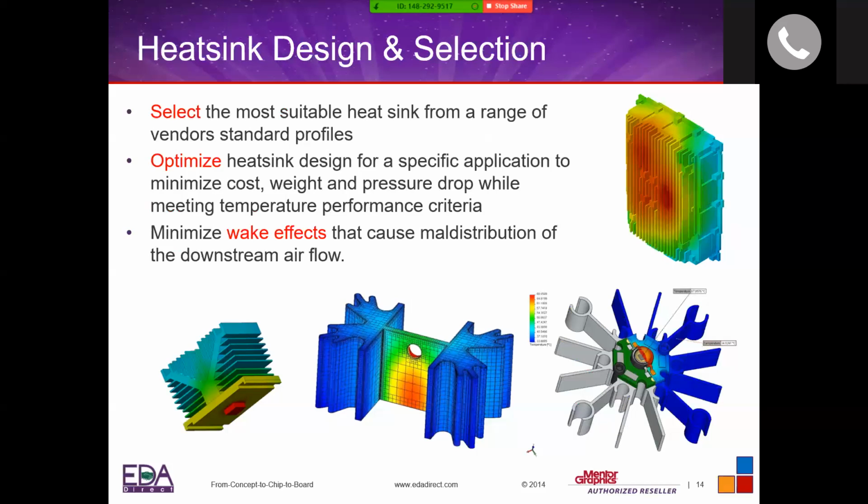And as the system powers up and starts running, it will affect the flow of the air inside the box. And that also affects how the heat flows. This is what we call the wake effect of the heat sink. And depending on how you design your heat sink, how many fins, how many blades, what's the thickness, what's the height, what is the material, it can alter the airflow in your system.